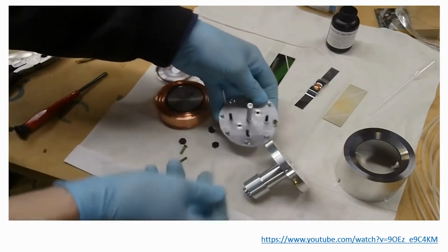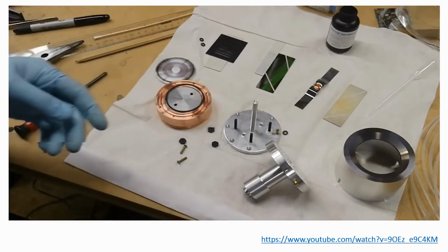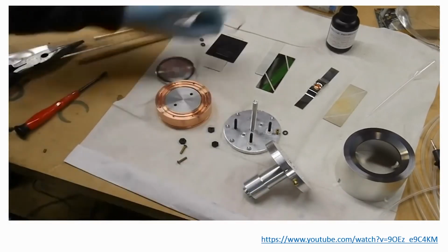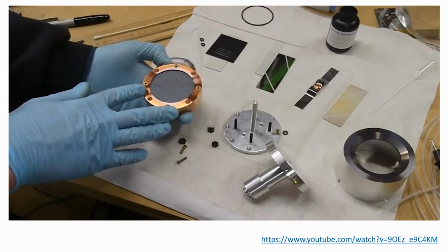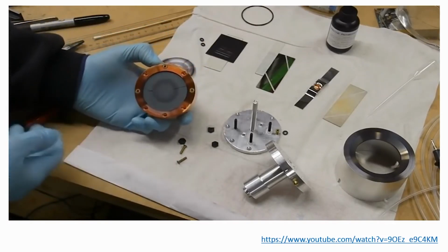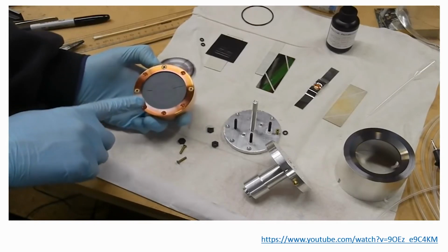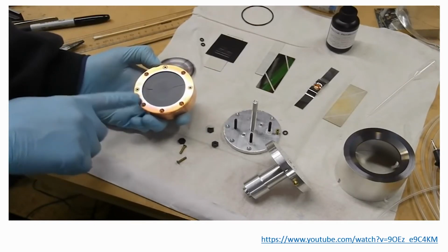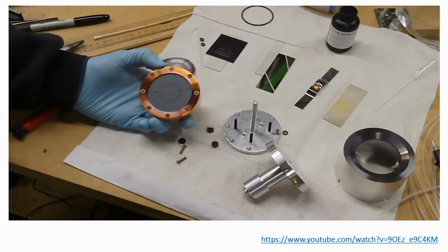So a lot of sputtering systems say they require water cooling, and I always thought that only applied to systems that ran for 8 hours a day. I figured that the thermal mass of this block would be enough to keep me safe for a 5-minute run. But as it turns out, not quite. I'm not sure if this was due to my clamping or too much power or something, but I think water cooling is kind of a necessary thing if you want to sputter stuff at any reasonable rate.